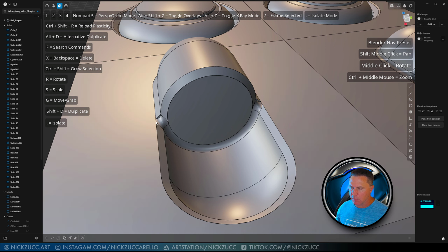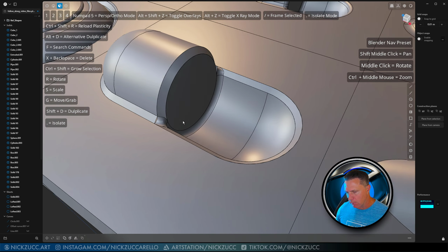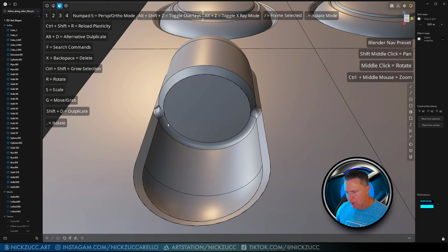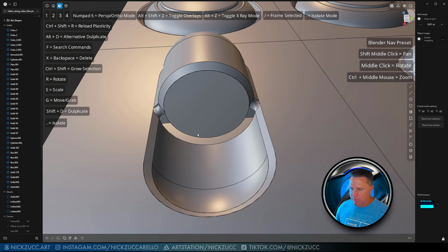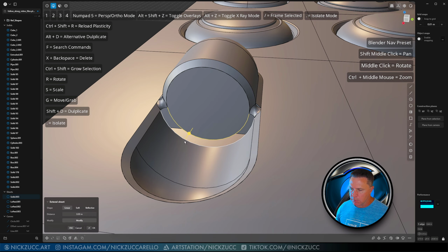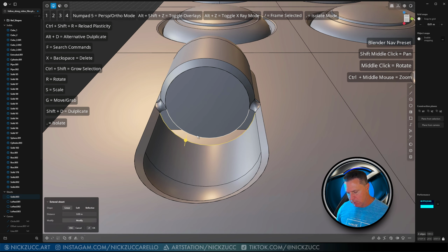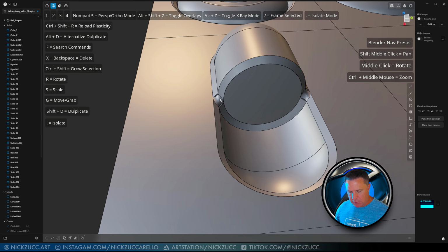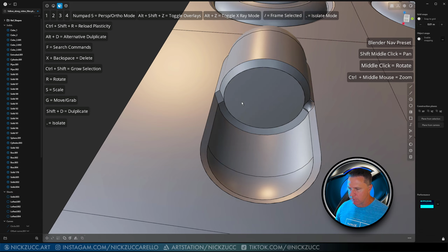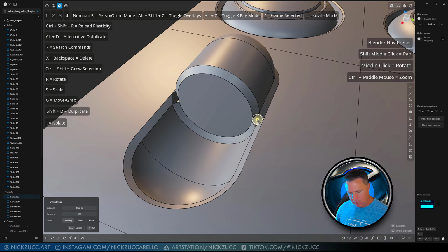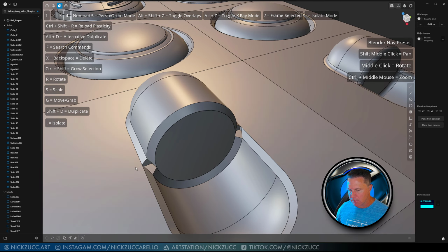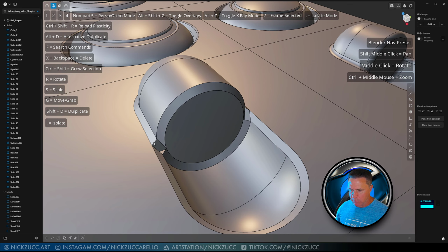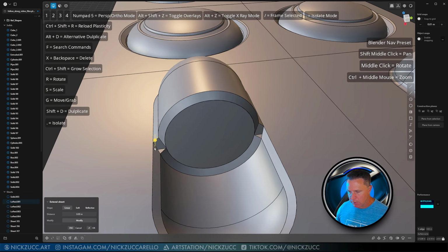And the reason I'm doing it in this order is I want this part right here to be the last part that I build. I'm going to hit Shift X for that, so I'm going to tap 2, hold down Shift, tap L, put this on G0 like that, and then I'm going to get rid of these shapes right here. So I'll tap 3, Shift X, get rid of this, Shift X, just like that, and then I will tap 2 on here.